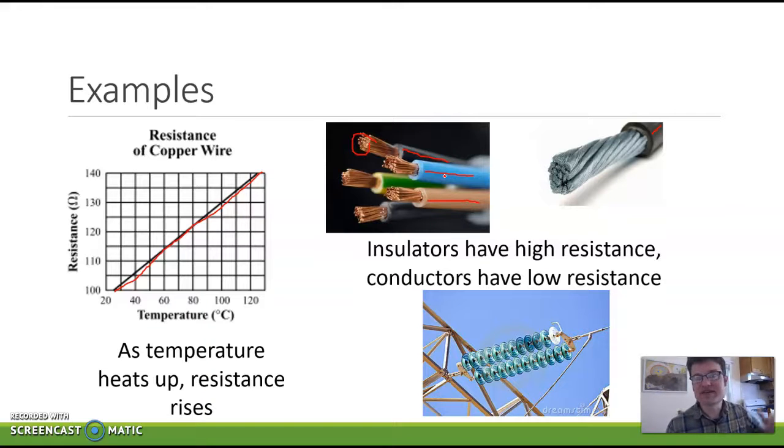Because there's such a high resistance, as that electricity jumps through the air, it gets super, super heated because of the resistance and the thermal power being let off. That's why you get the thunder and the lightning, because it's superheating that air. Basically, you're getting what we call an arc flash and an arc blast, which we're going to talk about later this week.